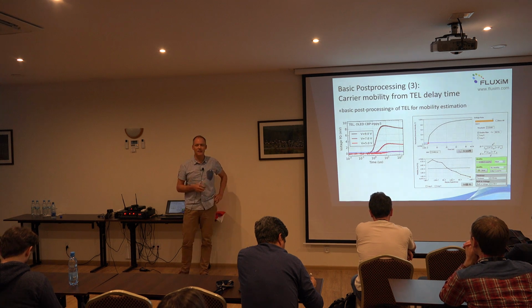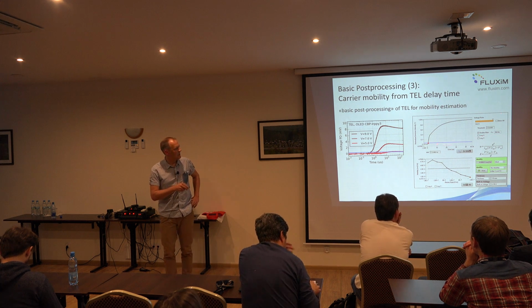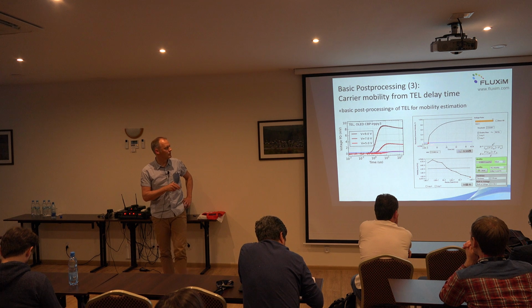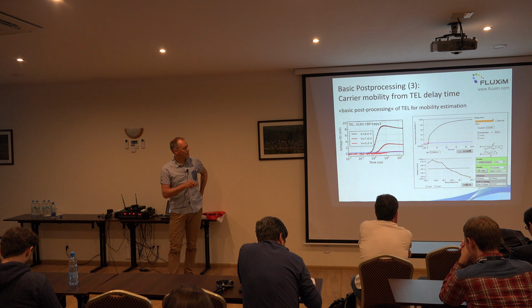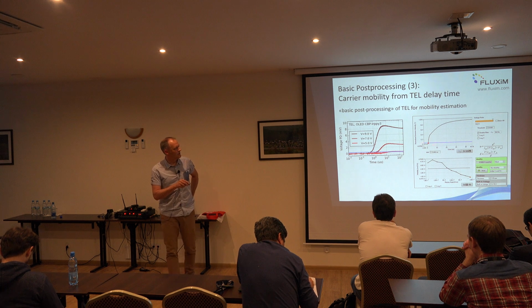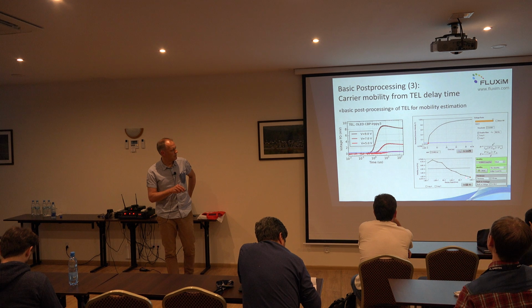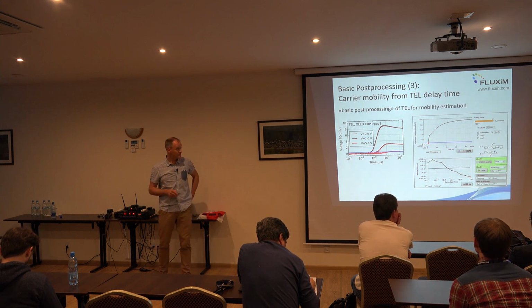This is done automatically by the PIO software. You can simply assign here a threshold current to use for the mobility estimation. So this is an example of 3 different voltages, the turn on. And on the right you see for 1 voltage, we get 1 value of a mobility that is automatically extracted by this simple formula.